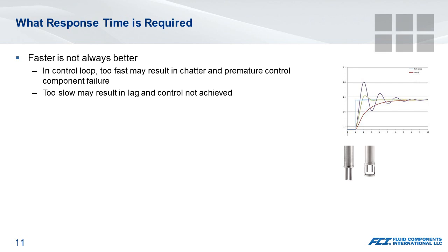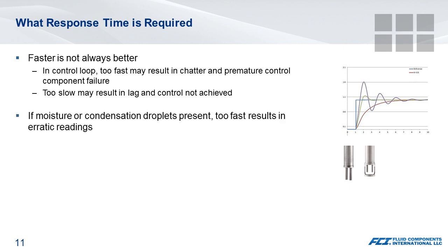There's a trade-off potentially with ruggedness as well. The larger mass sensor, larger mass material will be slower. The heat transfer will be slower, but they're more robust and rugged and can handle rugged handling compared to thinner wall thermal wells.